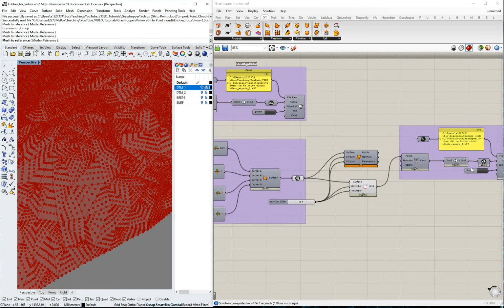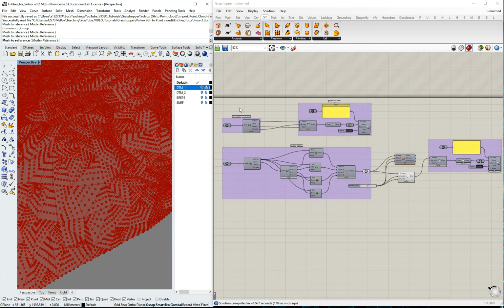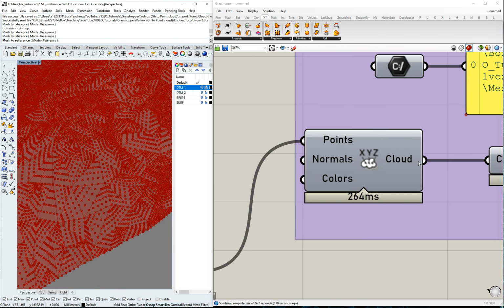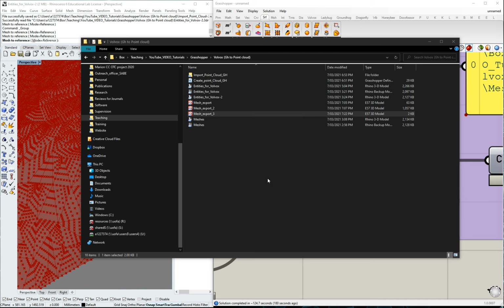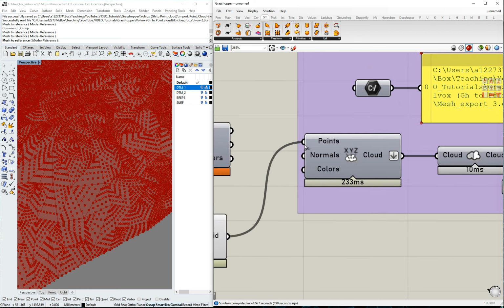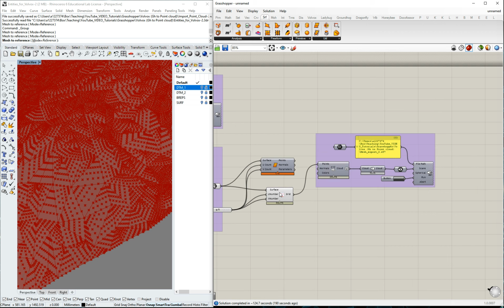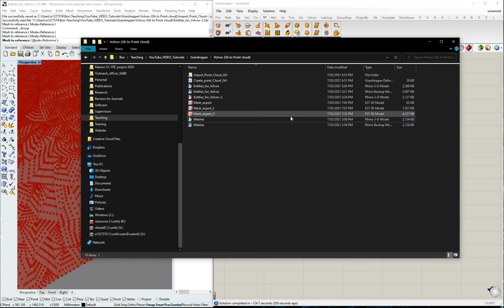Okay, now I know what might be happening here. It didn't happen before in this extract, but I noticed this should be flattened here. You have the points, and that's the error that is generated. So my mistake. Pay attention to this, it's very important to flatten here. Now the export will be all flattened. Let's do it again to see how it works. Now it's saving properly. If you don't flatten, it doesn't assume they're doing things correctly.